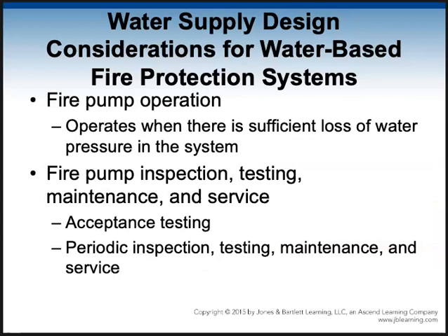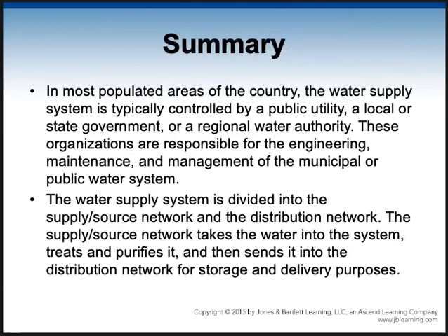The fire pumps need to be operated periodically and will turn on whenever there's a sufficient loss of water. They've constantly got to be inspected, tested, maintained, and serviced. Okay, so we learned about different parts of the country are going to have different needs for water supply systems. We're going to use different kinds of distribution systems where we use pumps and tanks and gravity fed. We're going to have to treat and purify the water and then send it through some kind of a distribution system.